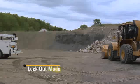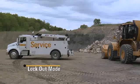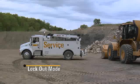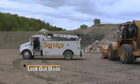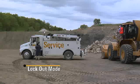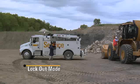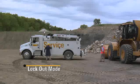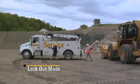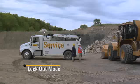Once the machine reaches lockout mode at 10 minutes of operation, after reaching 116% soot level, a service technician must be called to perform regeneration using the CAT Electronic Technician Service Tool. We're talking loss of production plus a service call, which is added cost and time. An operator should never let a machine get to this condition. But, as you will see shortly, it really can get worse.